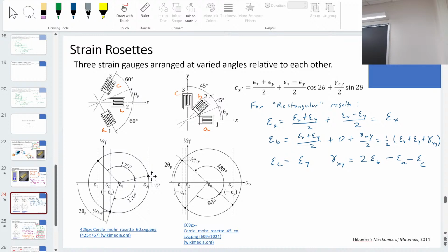If I draw the positive shear stress up, then the cut should be done exposing to that side. If you take a cut going the other direction, it's going to end up on the other side.